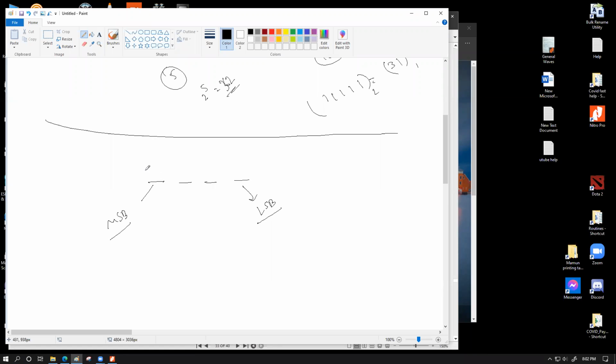The idea of most significant bit is that if you somehow mess up this bit, for example, in the original signal this bit is to be 1, and somehow at the receiving end this bit becomes 0, you're going to have a radical change of this whole data. Least significant bit, on the other hand, means that if you had a 0 over here and it becomes 1, or if it was 1 and it becomes 0, there are only two options. So if it just flips to the other binary value, you're going to have the slightest amount of change in the output data.